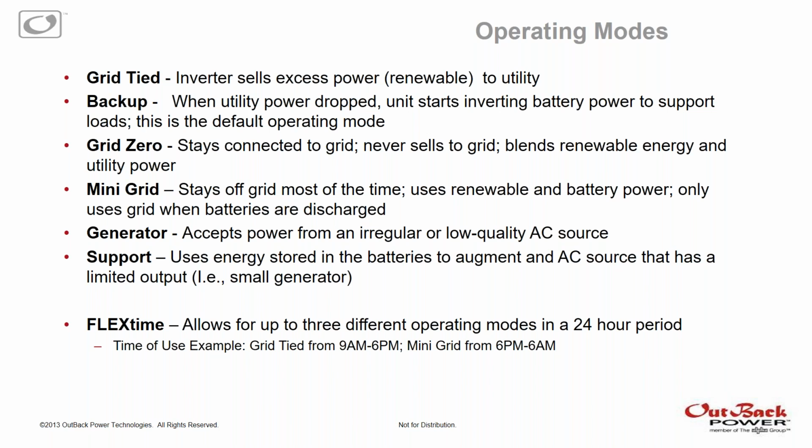There's also a couple of other operating modes that can be extremely useful given the topic of this webinar. First, I'll talk a little bit about generator mode, second from the bottom. This widens the input tolerance of the inverter to accept power from maybe a little lower quality generator. I know generator availability on a lot of the islands is challenging. Some of the generators that are probably being used may not be as well maintained as ideally, or could be a light duty generator that's being used a little bit more frequently than it's intended, so the output quality of power decreases rapidly. So this mode will allow generators or other AC sources that maybe aren't as ideal as we'd like to see. We allow that power to be used to charge batteries. So it definitely could be a useful operating mode in this application.